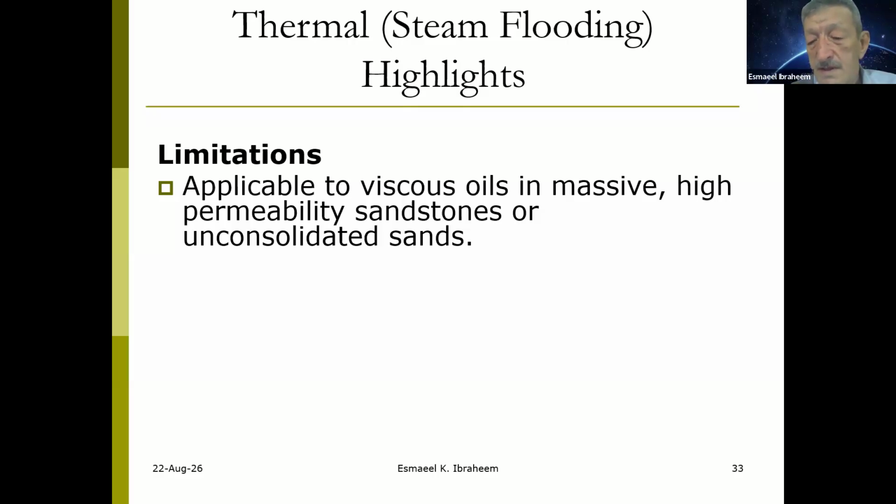It decreases the viscosity and increases the mobility of the oil, and makes the oil expand also. We need a high permeability formation, mainly sandstone, because, as you know, that's heavy oil. Most prefer sandstone formations or unconsolidated sand.